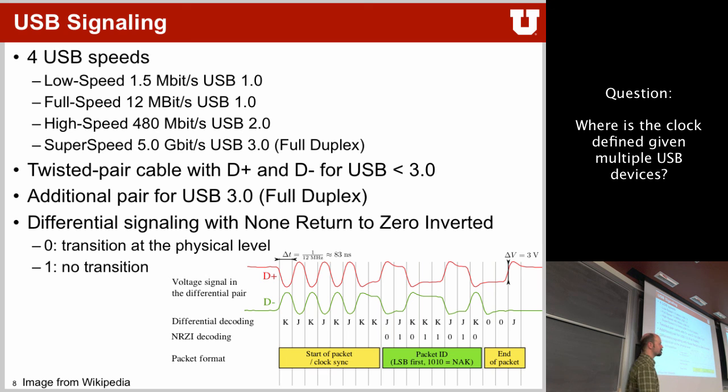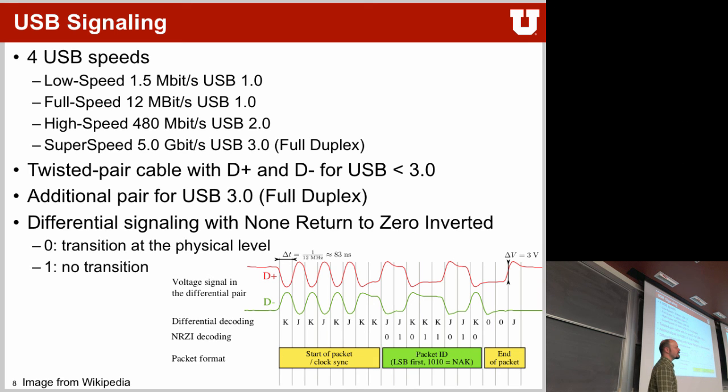Because you might have 2 different devices with 2 different clocks through the USB, right? Like a webcam would have a clock on it. Yes, it's an asynchronous protocol. So USB is a standard, and they define what type of clock you have to have on the other side, or how precise that clock has to be, depending on the device. So the device has a clock in there. There's no clock signal going over. Okay? So it's like UART. The other side has to have a clock that actually can decode the whole thing.